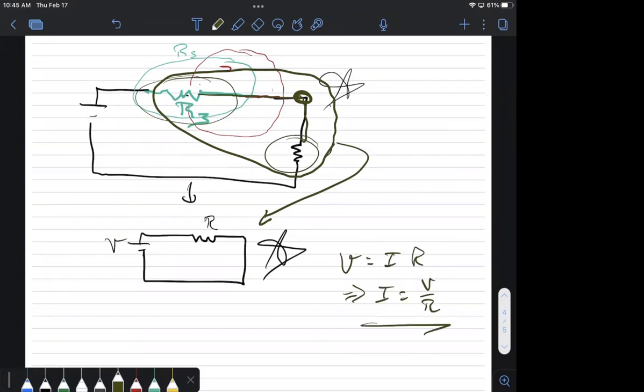So what we're going to do next time, now that I've shown you there's a difference between series and parallel, is what are the mathematical tools for series and what are the mathematical tools for parallel. I'm going to use them to take this complicated circuit and simplify it down one step at a time. It may take 4 or 5 steps of simplification, but I do it one step at a time until I'm left with the most basic circuit, one resistor with one voltage source. Once I have that, V equals IR gives me my answer.